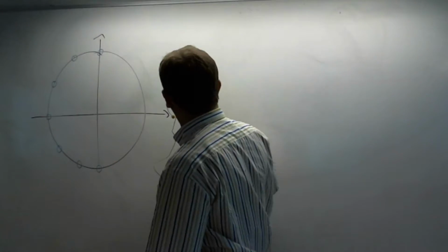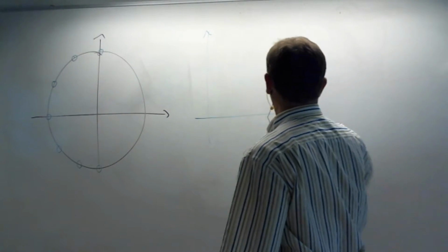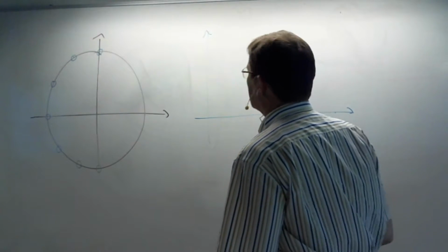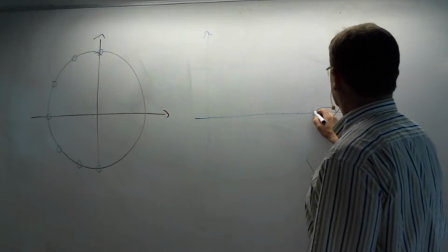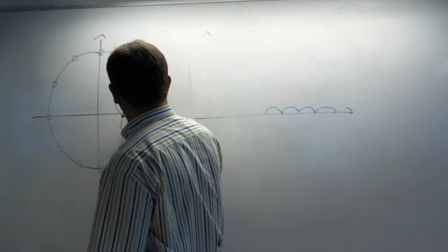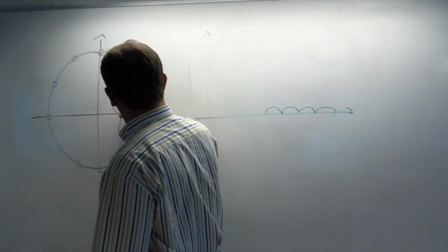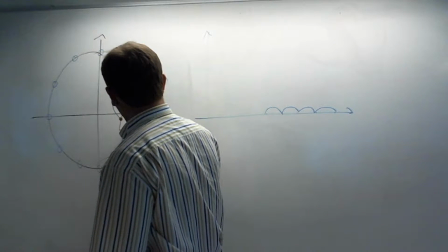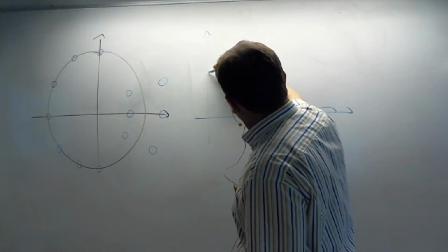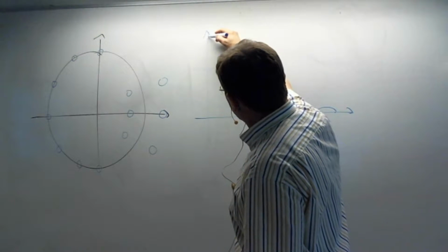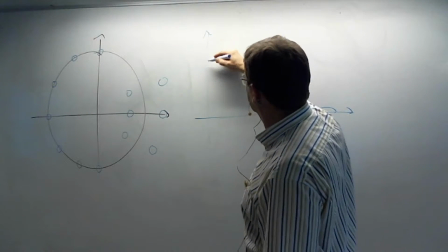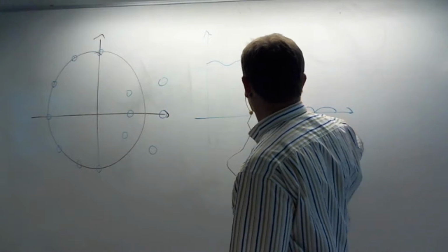When you put the zeros on the unit circle, you also get the zero points on the amplitude response. And if you put the zeros close to the unit circle but not exactly on it, you can do a kind of attenuation on the passband to make it flat.